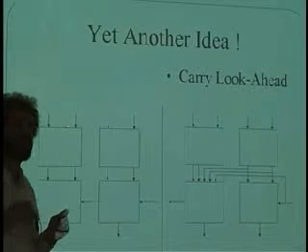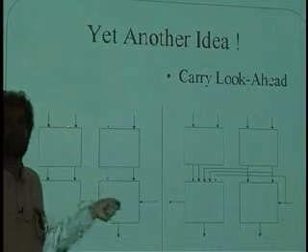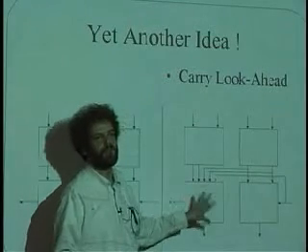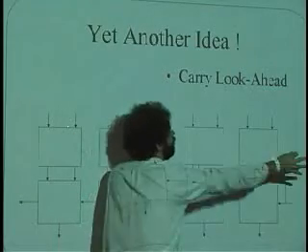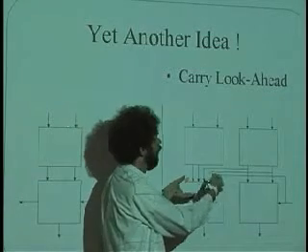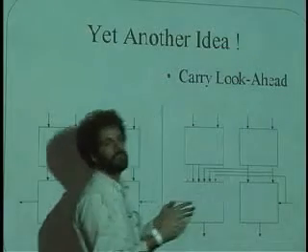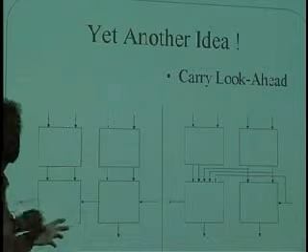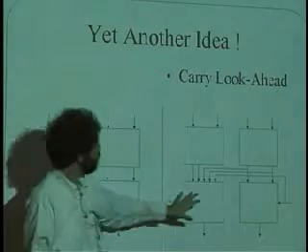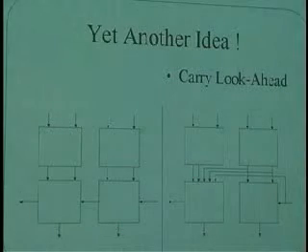I'm getting closer and closer to the first slide that I had, which was let's implement an adder with a table of 2 to the 70 inputs. Because if I take this to an extreme, let's say this is the high order bit, bit 31, I'm looking at all the generates and propagates of all the lower bits, and I end up with some big messy function here saying I want to figure out real fast what the output is. And remember, the table could figure out things very fast, but then we kind of jumped to this extremely slow way of doing it. This is somewhere in between. Okay, I have somewhat complex functions over here that are looking at G and P of different inputs in low order bit stages.